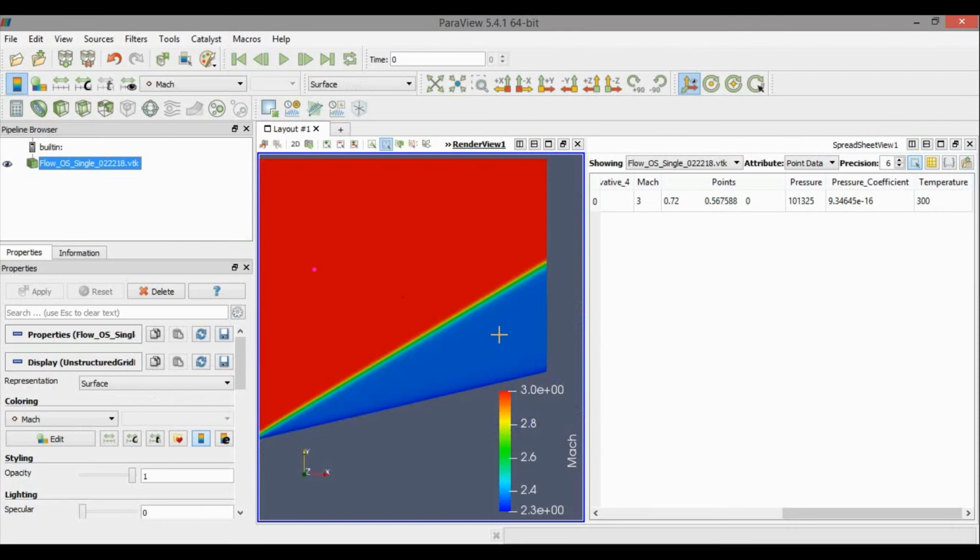So we'll press D again and click over here. It changes these values, and you can see now we have the Mach number of 2.3547, which is close to what we had, and the pressure and temperature are also close to the downstream values from the analytical.